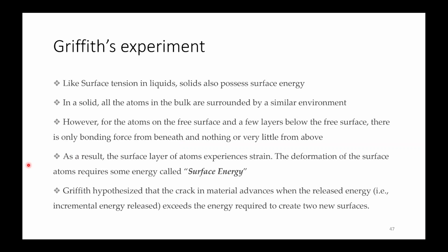As a result, the surface layer of atoms experiences strain, and the deformation of the surface atoms requires some energy called surface energy. Based on this, Griffith hypothesized that a crack in a material advances when the incremental energy released exceeds the energy required to create two new surfaces.